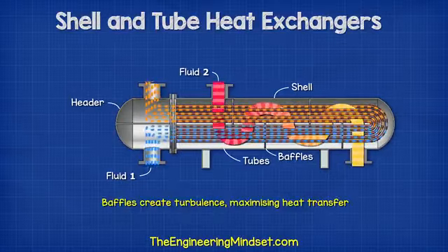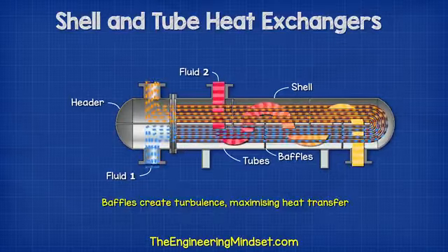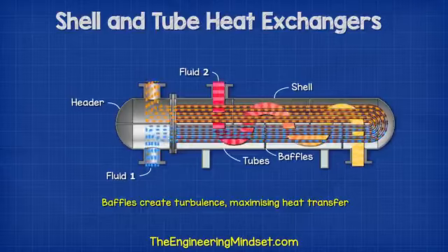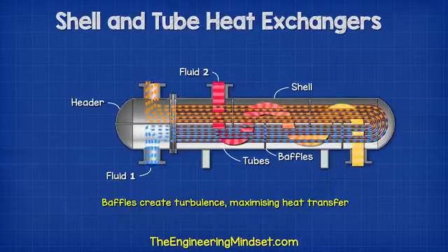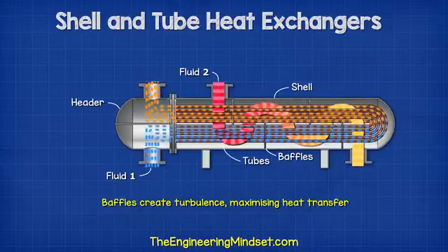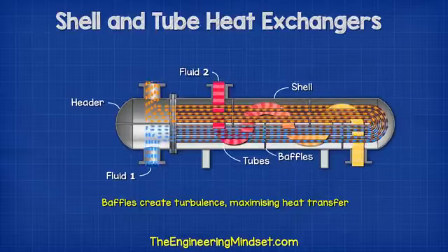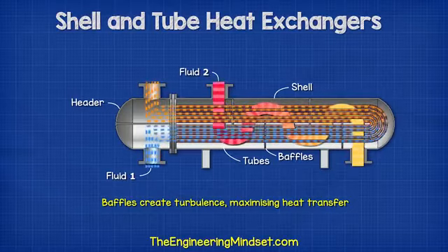The baffles will partially block the flow, which will force the fluid to turn multiple times. This creates a turbulent flow and ensures that fluid 2 mixes with itself, which ensures maximum heat transfer.